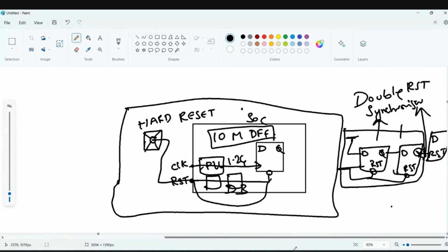In the RTL perception, we have to make sure of this particular clock. There is a clock pin for these flops, and they are coming from the same clock. So you want to synchronize this reset with this particular clock, because clock and reset have to be synchronized so that the reset is not toggling while the clock is coming in. It should be 0, I mean active low, so it should not toggle the flop. That means it should not toggle when the clock is driving this particular flop. That is the condition we need to meet. For that, you need to synchronize this asynchronous reset coming directly from the hard reset, by giving it this particular clock and making it stable after the 2 clock pulses.